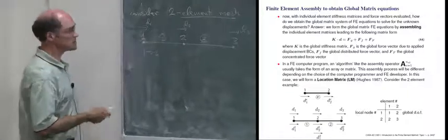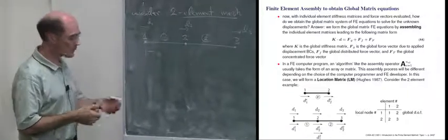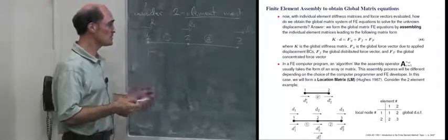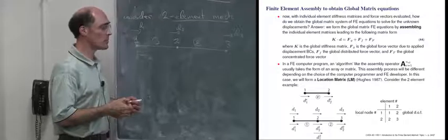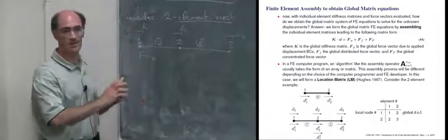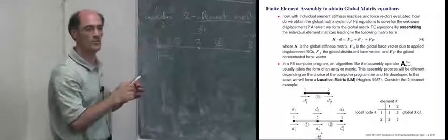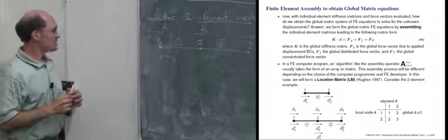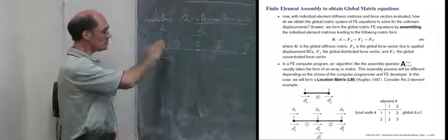We know that, which makes sense from a physical perspective, if we don't prescribe any boundary conditions, from a statics perspective, it's indeterminate. We can't solve the problem because basically you'll have a rigid body mode. If we had dynamics, we could throw this chalk across the room and that would be okay until it hits the wall, and then we'd have to do something else with the analysis.